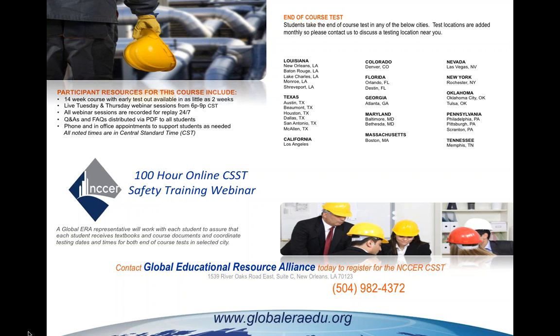Okay. And then, of course, welding safety. What are we talking about? We're talking about welding and cutting operations. We know it's common in the workplace, especially around steel erection. So there's some basic safety that we're going to follow at all times. We're going to make sure that, if we need any particular type of eye protection, we're going to wear it. Not only safety glasses, it may be shields. It may be a welding hood, depending on what's required. In addition to that, also wearing safety glasses underneath those helmets as well, if it's just a shield, depending on whether it's fully encapsulated or not.